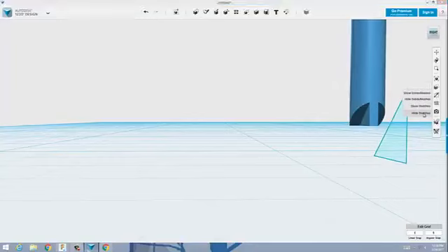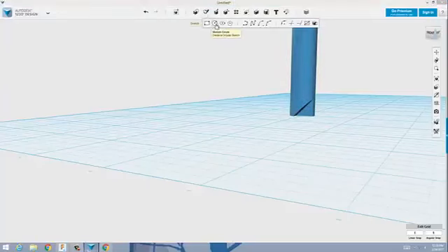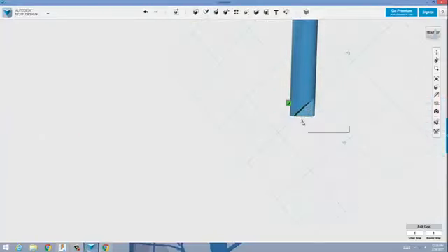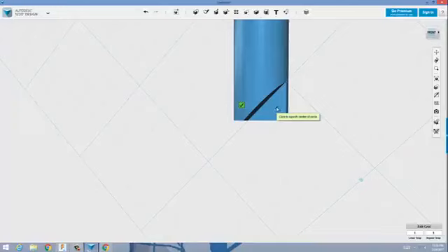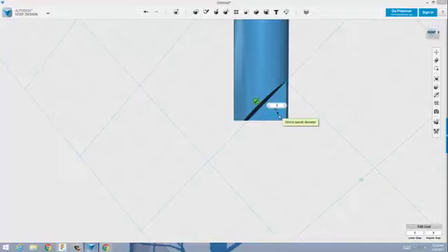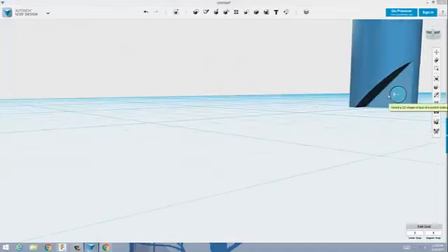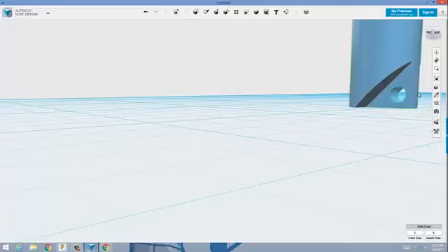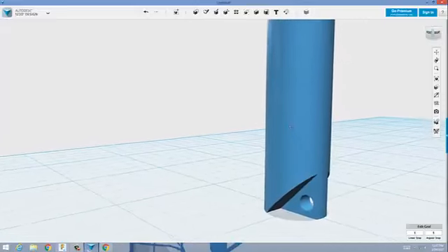I'm going to hide that sketch, and I want to put a hole right in here. And so I'm going to draw a circle. I'm going to draw it on this plane right here, and now this is the challenging part. There's no way in 123D Design right now to have that exactly where we want it. So we're going to place it almost in the center, but enough away from that line there that it's not going to interfere. Actually, I'm going to put center, and I'm going to key in 3 millimeters. Bingo. I'm going to extrude that circle into my whistle. Notice that it's subtracting material, and I'm almost ready to go, and I'm going to hide that sketch, so now I just have my materials.